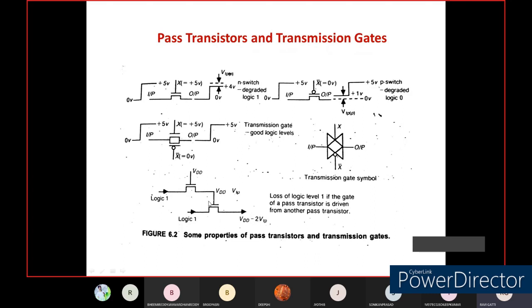If you combine more elements in this manner, then at some instant you may not drive the output terminal effectively. In such a case, your output voltage will be 0. So when you are driving a large number of elements with these NMOS pass transistors, you need to make sure that the gate voltage you are giving is very large compared to the number of elements you are combining or cascading in the pass transistor logic.